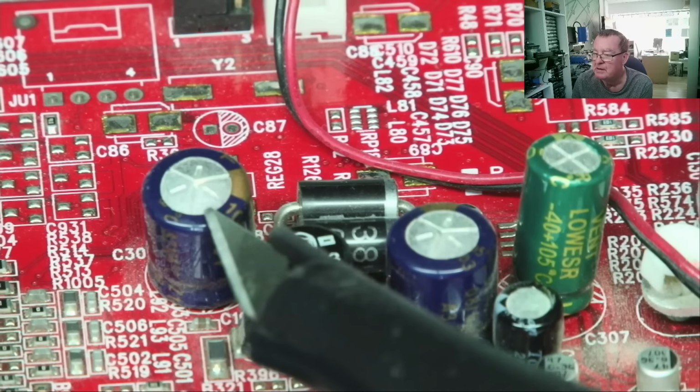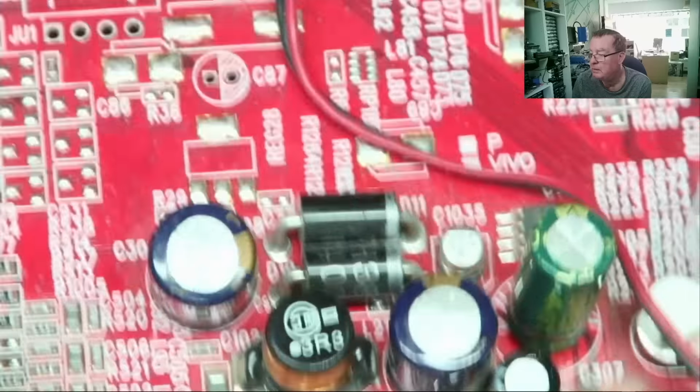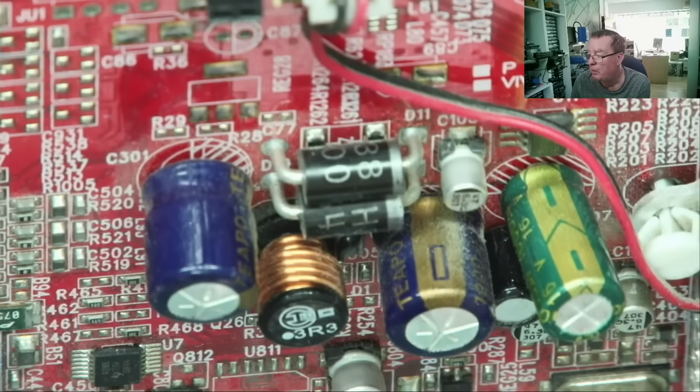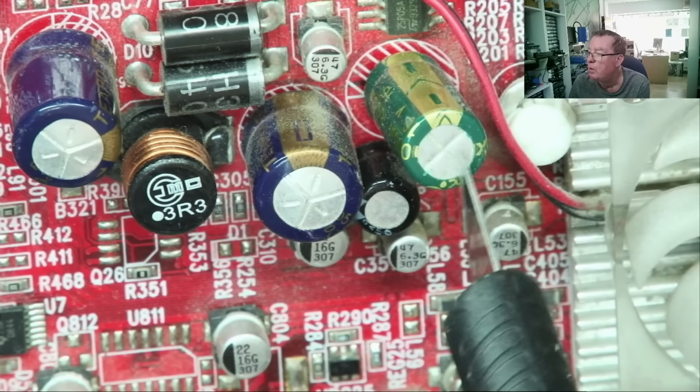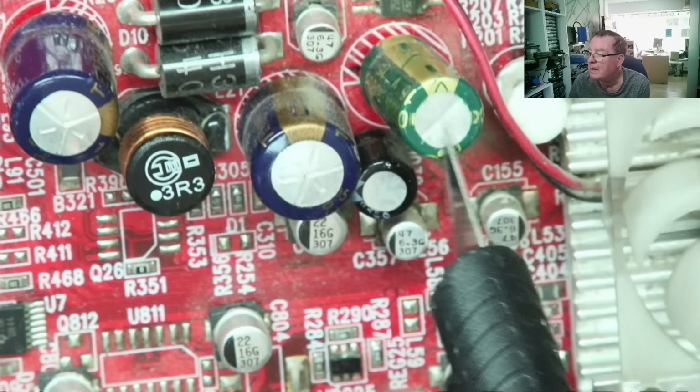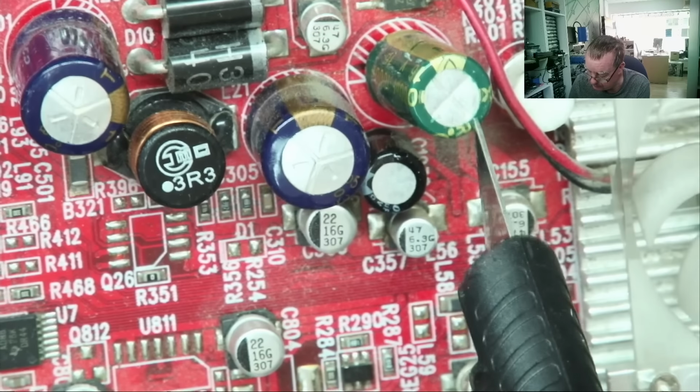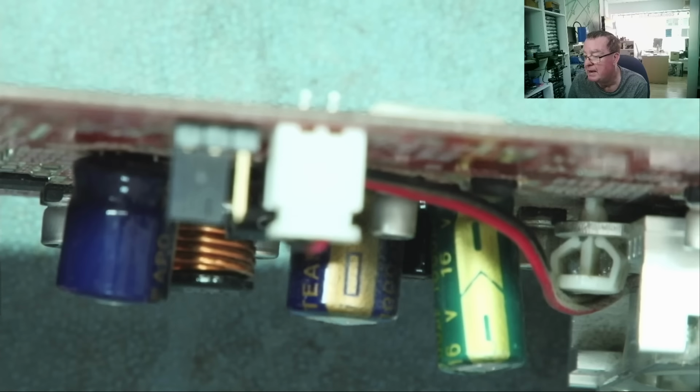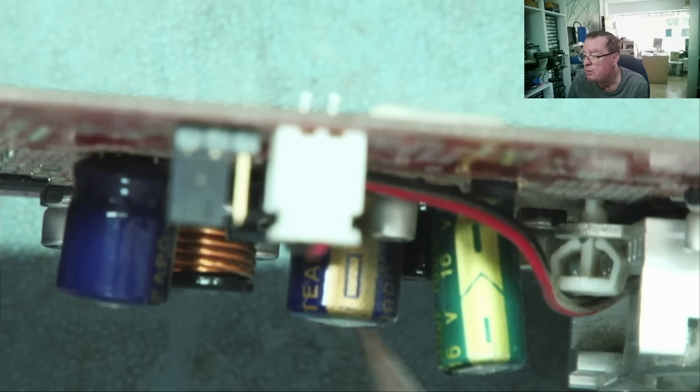The reason people feel that capacitors, and in particular electrolytic capacitors like these, fail, and these have failed or are failing, by the way, so you can see this one, which is a new one, has a very flat top, and these are bulged outwards. Like this, if we just get to an angle there, so these are like domed.